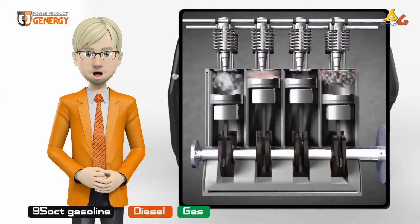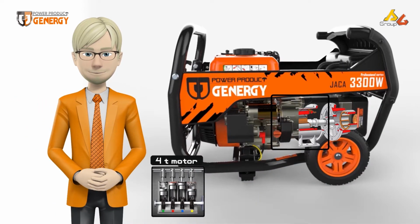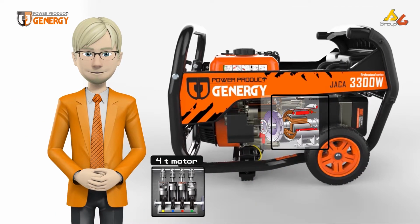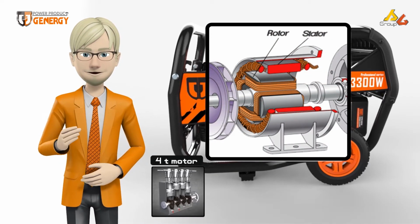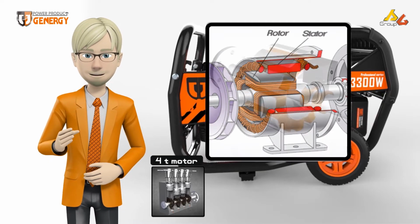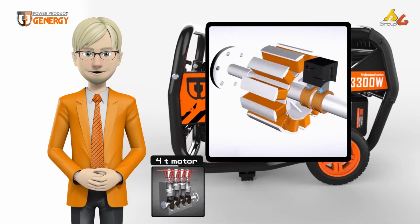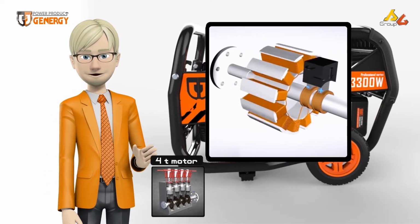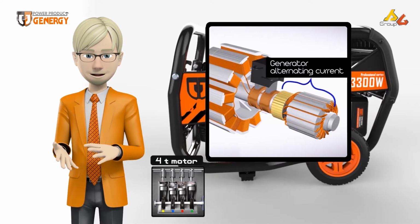The other essential part of an electric generator, alongside the engine, is the alternator. The alternator is composed of an outer body called a stator or an armature, and an inner mobile called a rotor or an inductor that rotates when driven by the force of the combustion engine. Thanks to excitation through brushes, a magnetic field is generated between both bodies, which as a result causes the production of an alternating current.